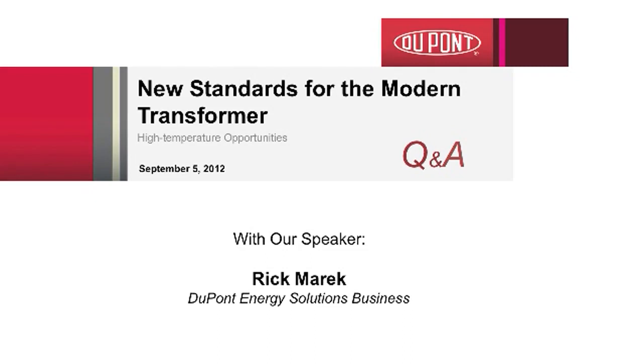And even Mylar would not be recommended due to hydrolytic instability. So I would avoid laminates completely in the liquid-filled. Part of the issue, too, would be the high potential for trapping air between the laminate when it is created.